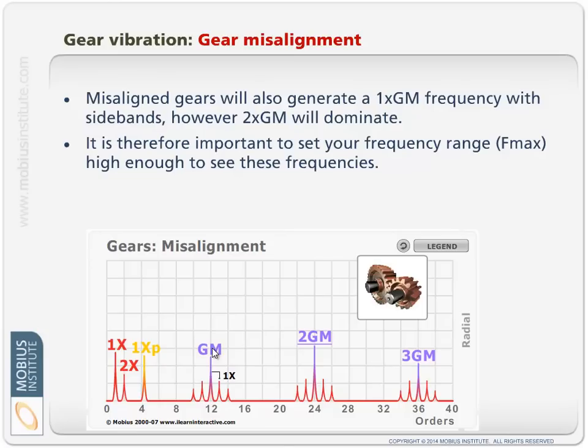But on the other hand, you have to be able to reverse that process. You need to look at the vibration and say, why is it so? Why am I seeing these changes? Why is the modulation changing? Why is the Gearmesh changing? And go backwards. That's the truth in the case of analyzing gearboxes, but it's the truth no matter what you're doing with vibration.